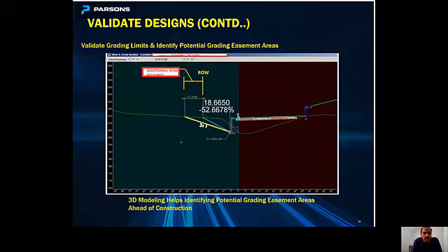This is one of the areas where we were able to identify steep slopes due to the right-of-way constraint. And the cyan line shown here was producing a very steep slope, 52%, and it was not complying with the slope criteria for the project. And then later on we were able to suggest an acceptable side slope in front of the culvert downstream end, and we were also able to provide the amount of additional right-of-way needed based on the 3D modeling techniques.